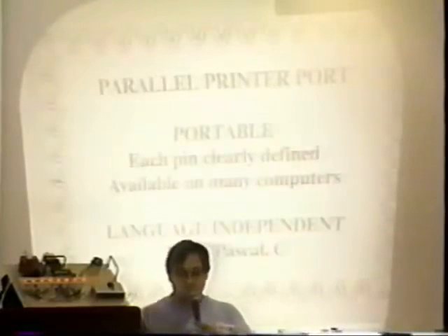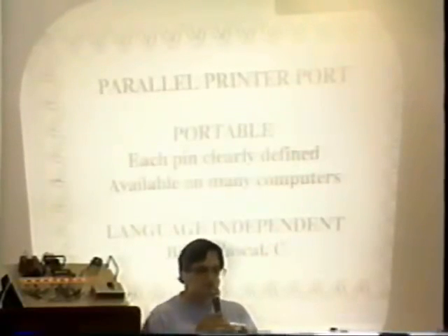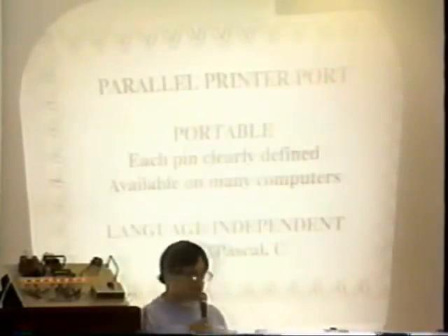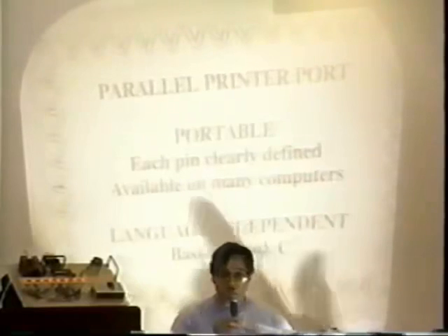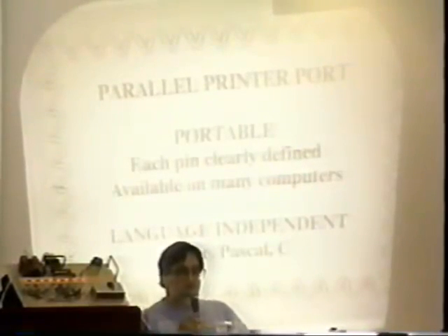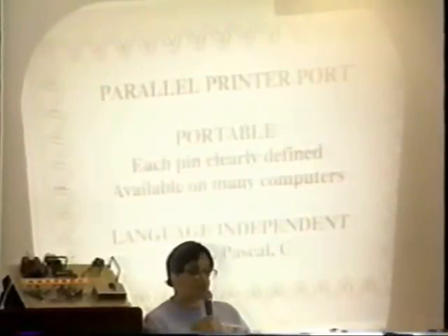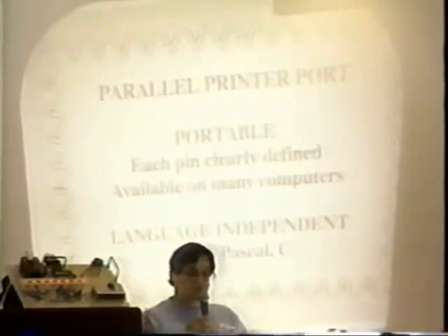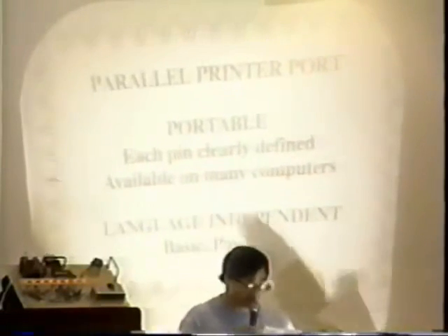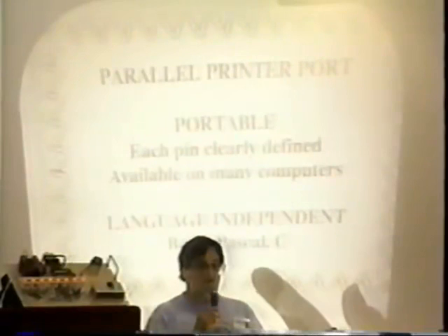Sometimes they call it a DTE. What is it? One's a computer and the other's a terminal, and I don't know. They got a whole bunch of standards. So we can't even talk the same with the serial. With a parallel port, every single pin was defined by the Centronics company when they made their first parallel printers. And everybody uses the same pins, and they all mean the same thing, and they all do the same thing. Nothing is different on any computer. They're all the same.